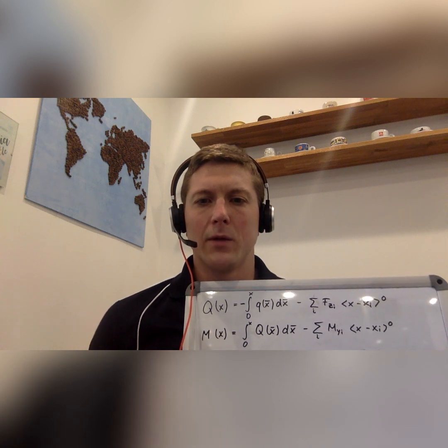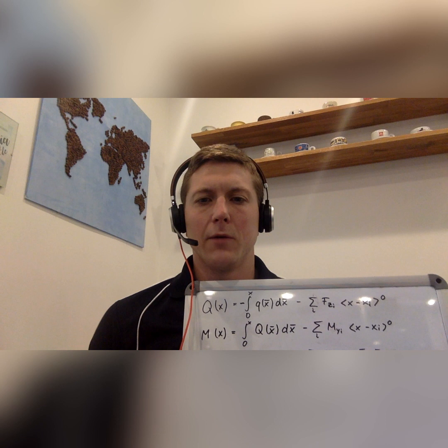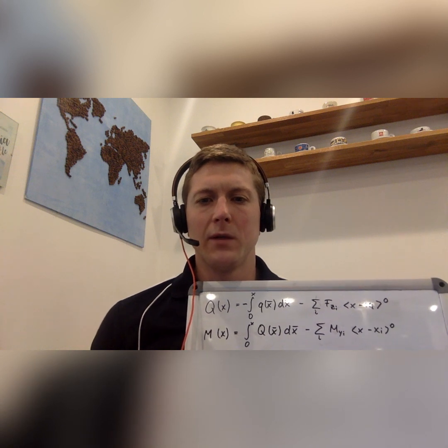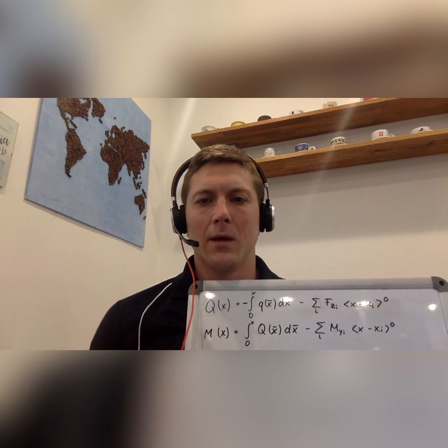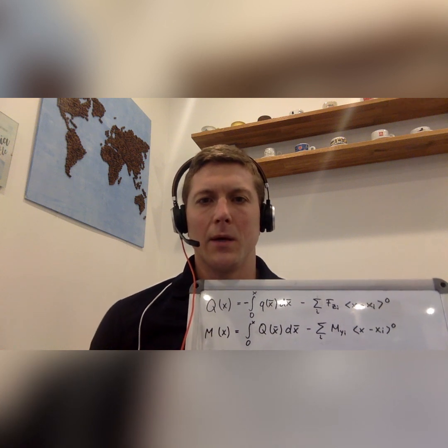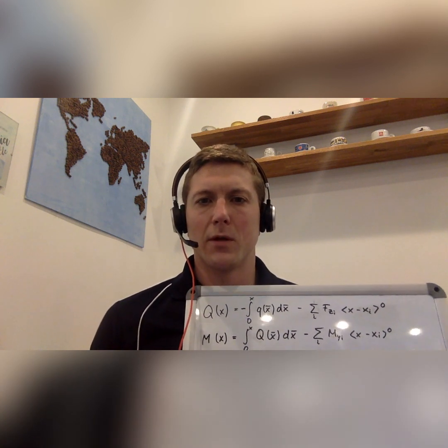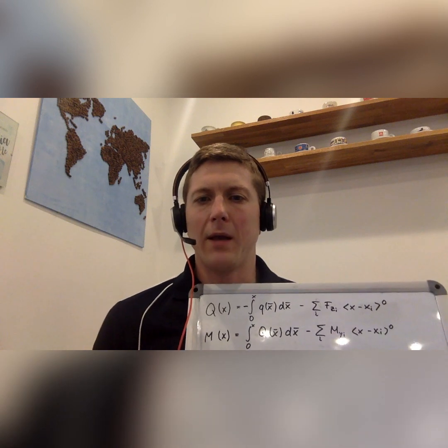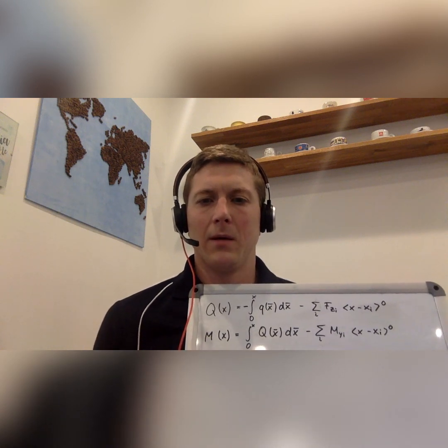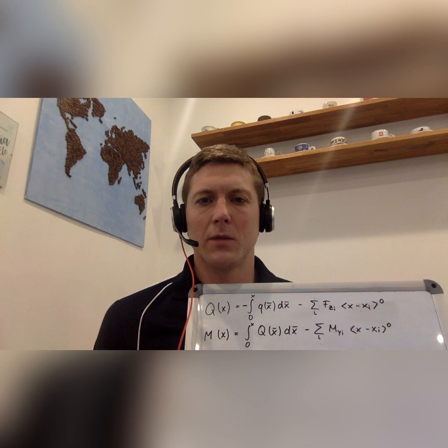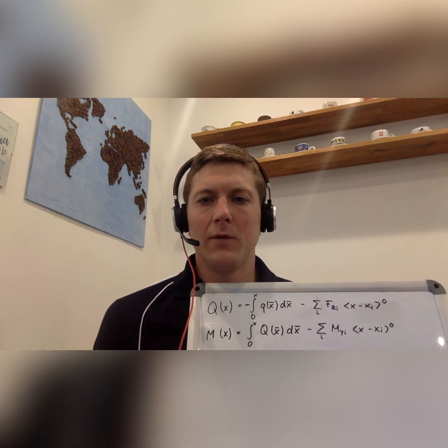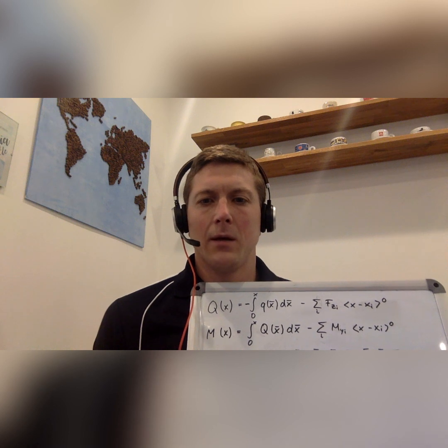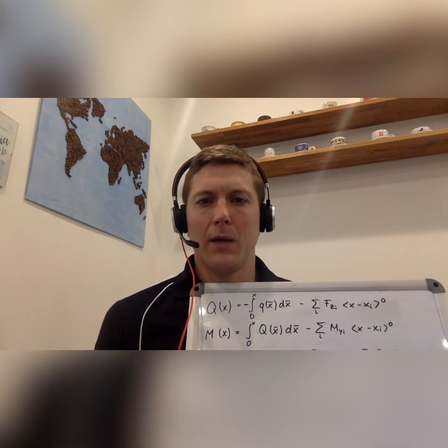And what you can see in our equations, we use here a definite integration, so we integrate from 0 to the position x, and this x would be then from 0, so the start of our beam, to the length of our complete beam. But of course, what is also possible is that you make an indefinite integration scheme and then identify the constant via the boundary condition.